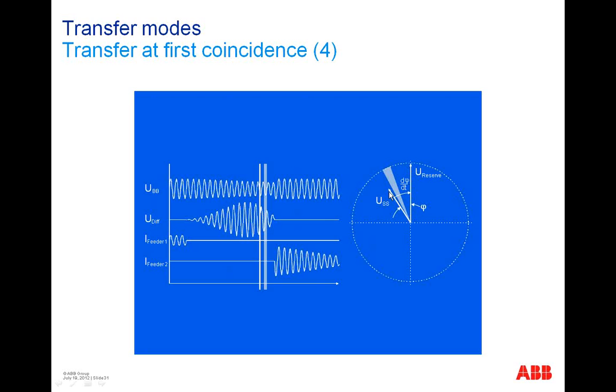So the HSTD knows exactly the speed of this phase angle and the time for closing the breaker, and then the command is given in advance so that the breaker physically closes at the moment of synchronous conditions, and then the bus bar is fed again.